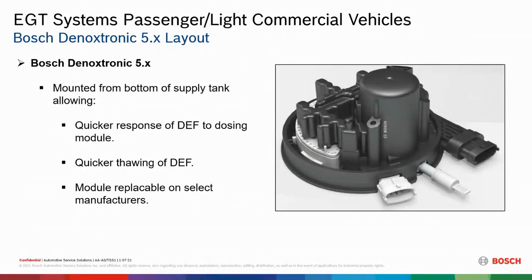So it's at, let's say, minus 20 degrees. They only give you so much time for that fluid to be thawed. I don't know what the time is for every temperature because it's different for everyone, but just an example, I'm just throwing it out there, I'm guessing at this. So if it's minus 20 degrees, they give you 28 minutes to thaw that fluid and start dosing. So there are time limits that they give you before this vehicle has to start dosing that fluid.